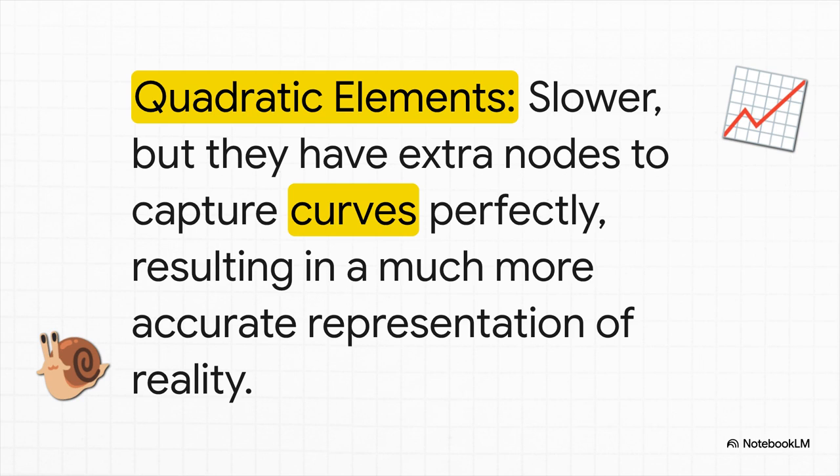These extra points allow the edges of the element to actually bend and curve. This means they can capture the true, smooth geometry of your model way more accurately. Of course, that extra accuracy comes at a price. More nodes mean more calculations, and that means longer simulation times.